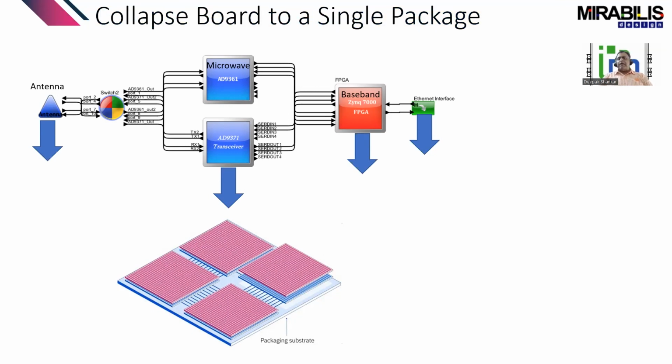That also explains why the standard for the interconnect across multi-die is UCIe, which is very close to PCIe 6.0. In this case, I have a complete communication system, which I can transition into a single package. Each of these components that you see, discrete components that you can buy off the shelf, are now integrated into the single package.